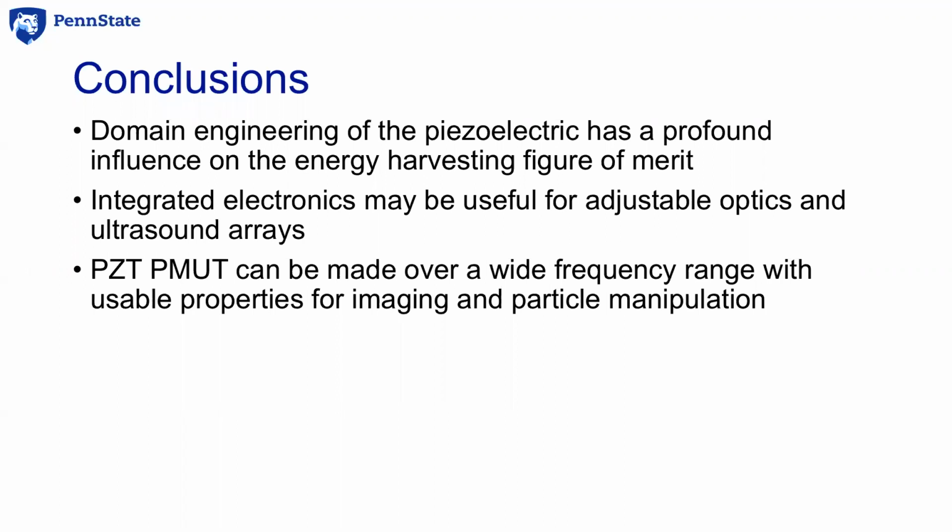I also demonstrated that the ability to integrate electronics on actuator arrays offers the possibility of doing low wire count devices for a large number of applications, including the proposed LINX X-ray space telescope. And my last topics were on piezoelectric micromachined ultrasound transducers, which we've demonstrated over quite a wide frequency range, and also the piezoelectronic transistor, in which the piezoelectric itself becomes the computation element.